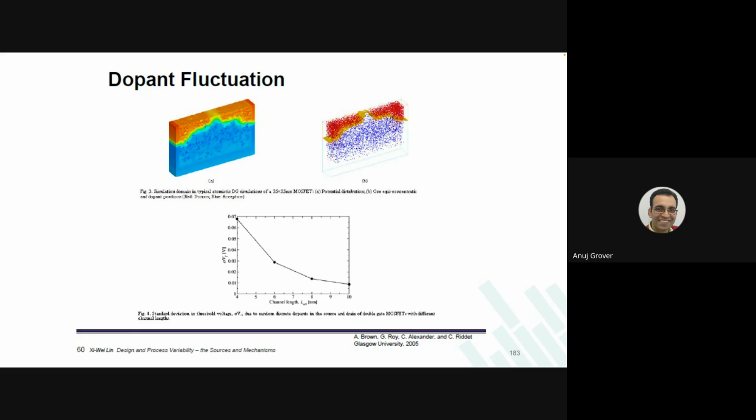In 28 nanometer, you will realize that with the same technology, the same machining being used, an FDSOI design can go to about 100 millivolts lower than a bulk design.